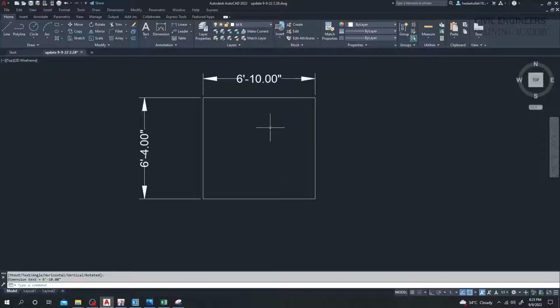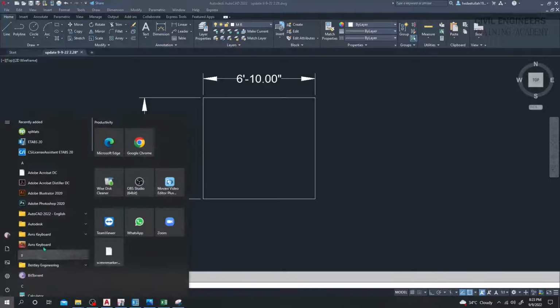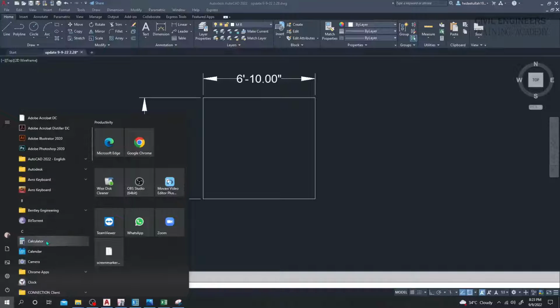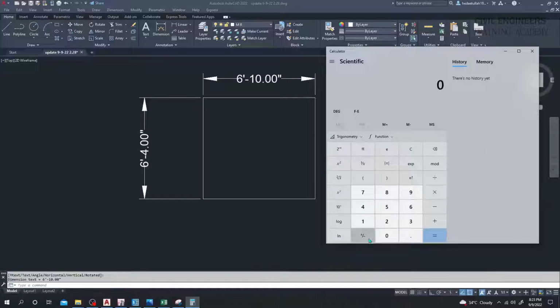So from one pile to another pile, our center to center spacing of pile will be 3D or 2.5D. So I will consider here 2.5D.